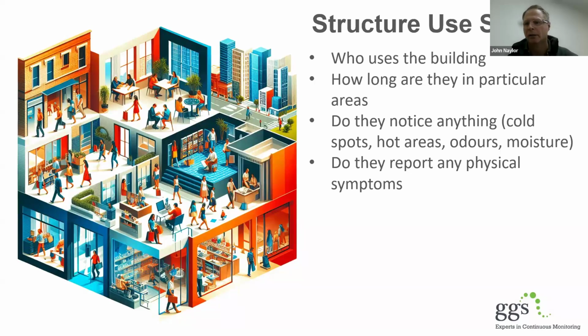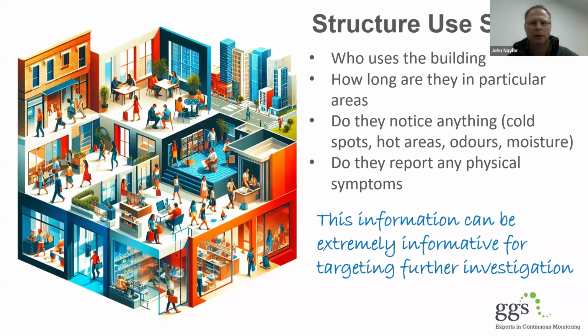Okay, are they noticing cold spots, dead spots, hot spots, odors, and where are these occurring? Again, ideas for where you might want to focus or target some investigation, some monitoring, and of course, any physical symptoms, shortness of breath, all that kind of stuff is in there as well. So slightly different from what you might be used to, but very useful and particularly used in indoor air quality assessments as well.